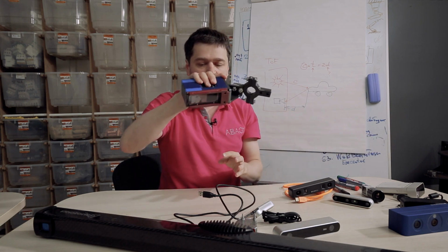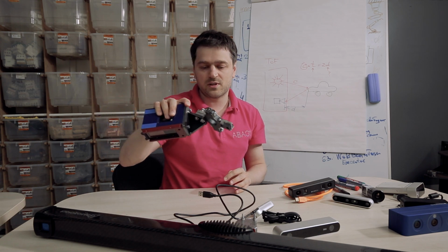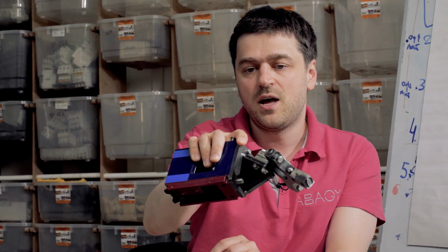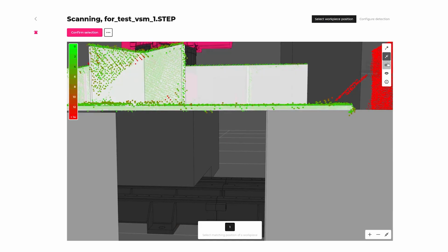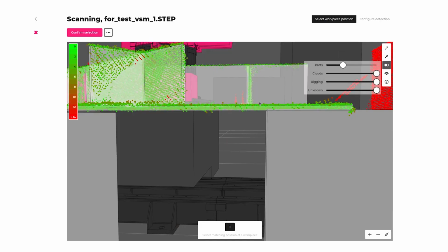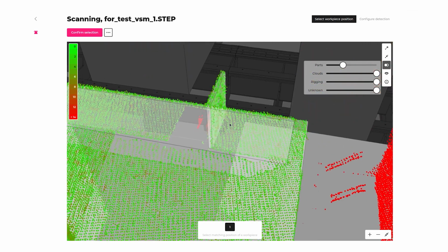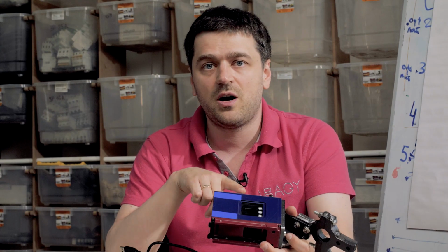So imagine that my arm is a robotic arm and that I'm moving the scanner and shooting the profiles of this object. In this case, I need to know the pose of the robotic arm for every profile I get, to stitch them all together and to get a beautiful 3D point cloud of my object. And for this, the best way is to use digital output of the robot or digital input of the sensor, or vice versa, to synchronize the signals.